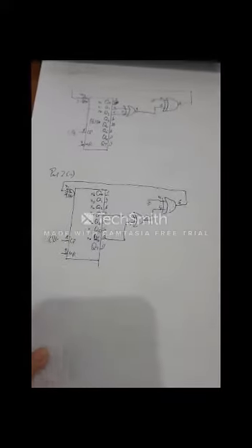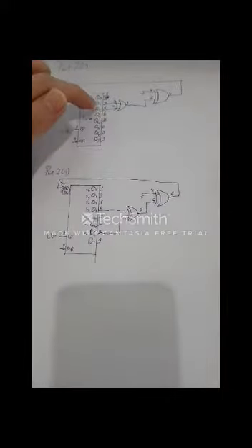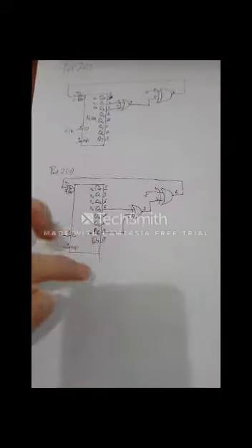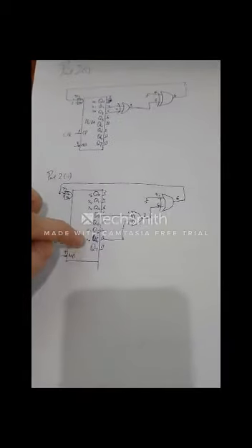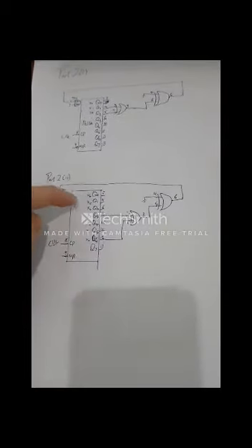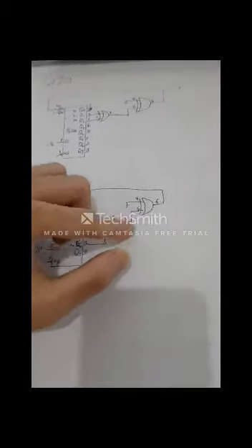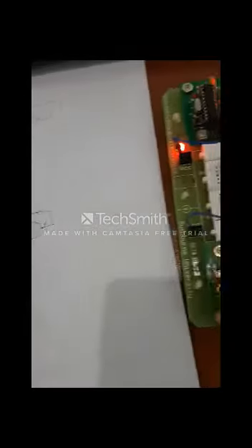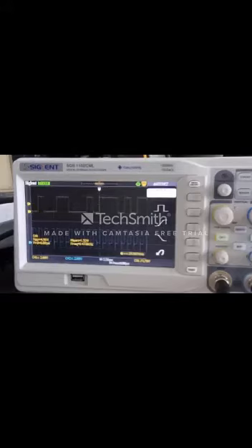In the second part, as you can see in these two diagrams, we are only moving Q1 and Q2 to Q6 and Q3, just to make sure that our bits start from X0 to here to become X7. For the exclusive OR gate, we are using the same part. So this is our schematic. As you can see in this oscilloscope output, we are actually getting a random output for this part.